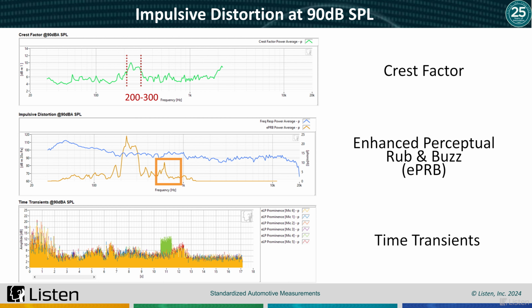We can also see a smaller, sharper bump at 600 Hz, which is not perceptible using crest factor measurement, even though I could hear it during the sweep. This measurement technique is also considerably more reliable in a noisy environment.